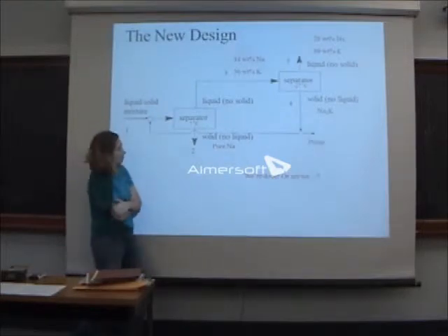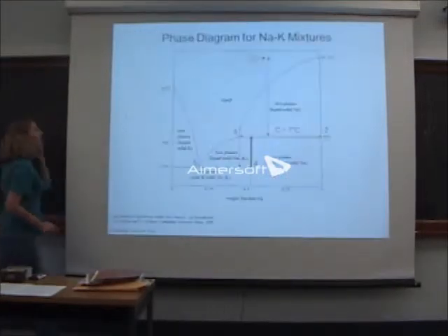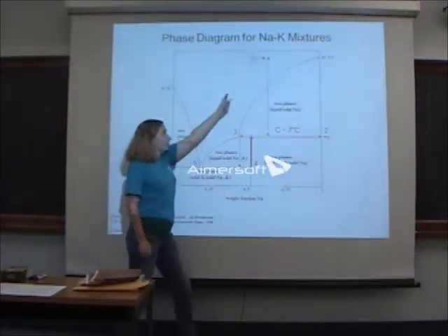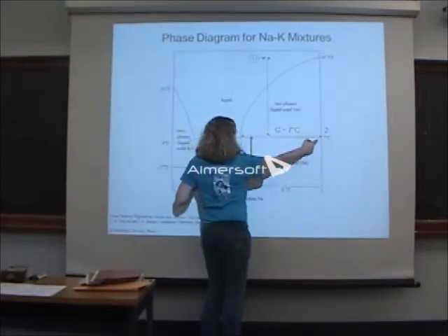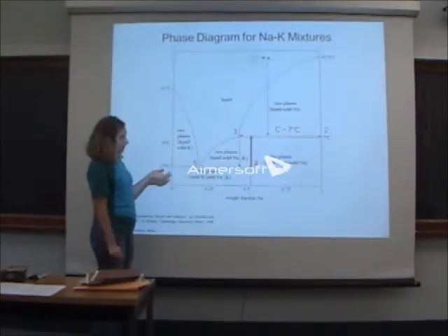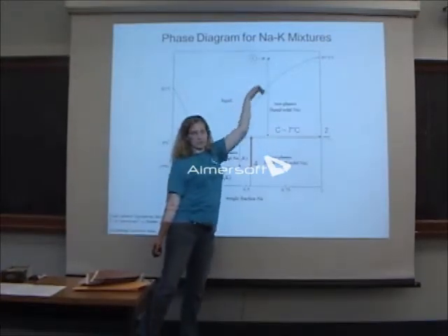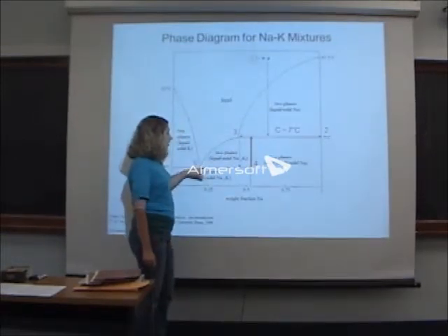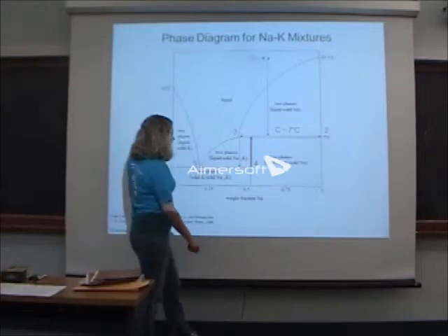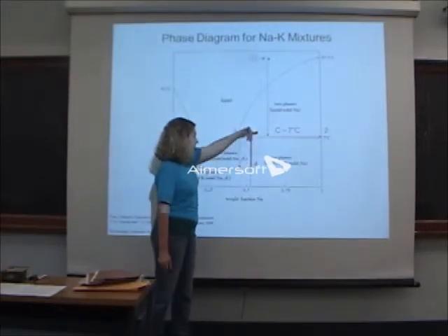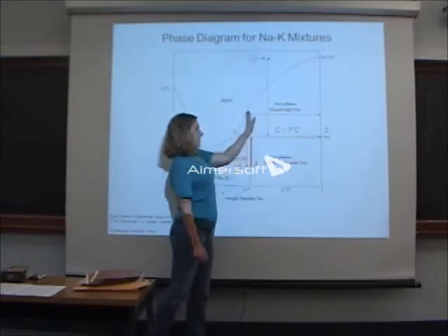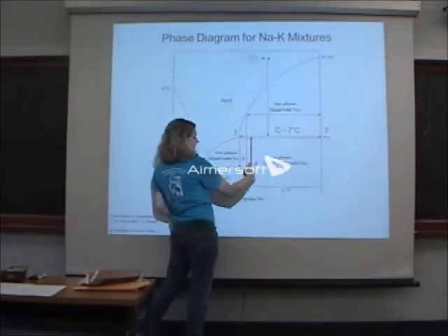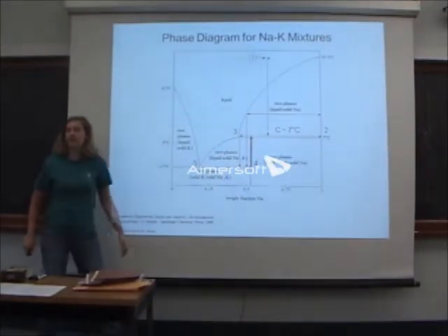A purge. Good job. Okay, so one other thing that I want to look at with this process. So I have my input, right? And I have my 2 outputs. So in order to actually run this process, I'm going to have to get a cooler to cool this to here, to about 7 degrees, and I have to get another cooler to cool this to here. So what would you guys think if I, instead of going all the way down to 7 degrees, went to around like 20 degrees and split it there and there? How would that affect my process? And then I just recycle this loop instead of having that one. How would that affect my process?